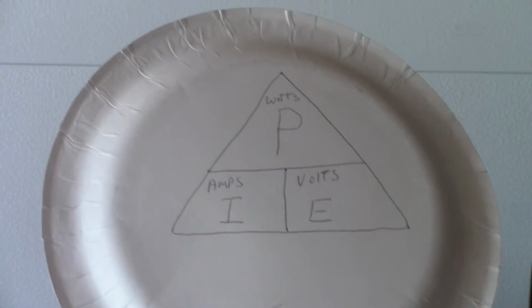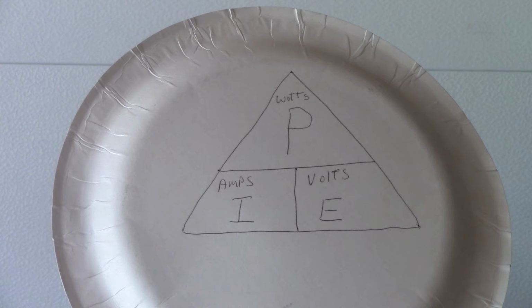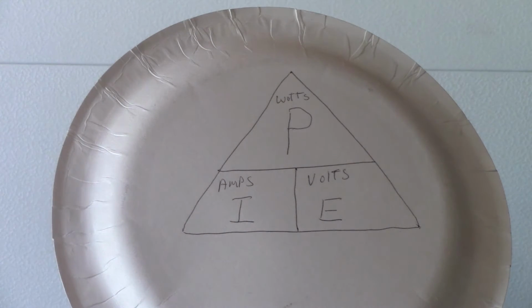So if we know that our total watt draw is 6 LED lights at 10 watts each, that's 60 watts divided by 12 equals 5 amps. So I need to fuse my circuit and get the proper wire size for the circuit, and that's what Watt's Law does. It helps us find our values, and hence we can now determine wire size, fuse size, charge controller size, and inverter size.